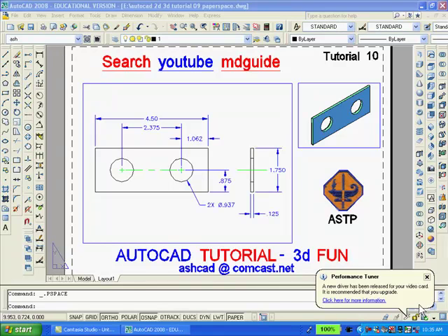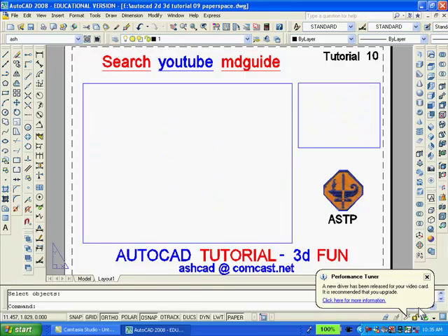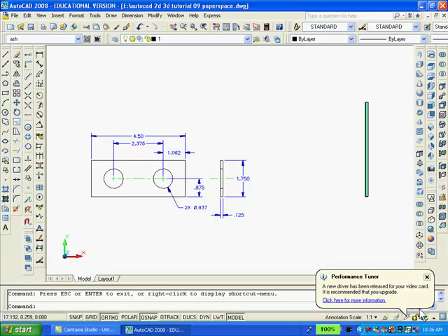What you are looking at is my 2D drawing and solid model in Paperspace. The first thing to do is to erase both the large and small viewport. You can see that the drawings disappear from Paperspace. All that remains are two rectangles which I drew previously to serve as templates for when I redraw the viewports later on. To get into Model Space, I'll click the Model button. Notice that the drawings still exist in Model Space even though they were erased in Paperspace.